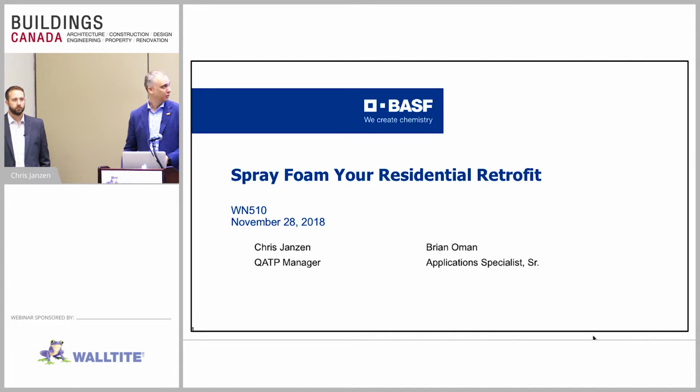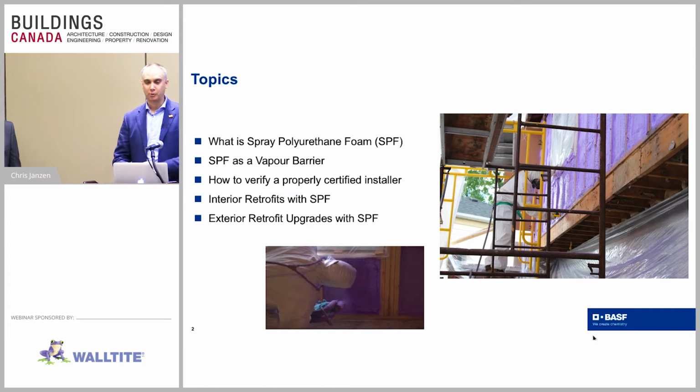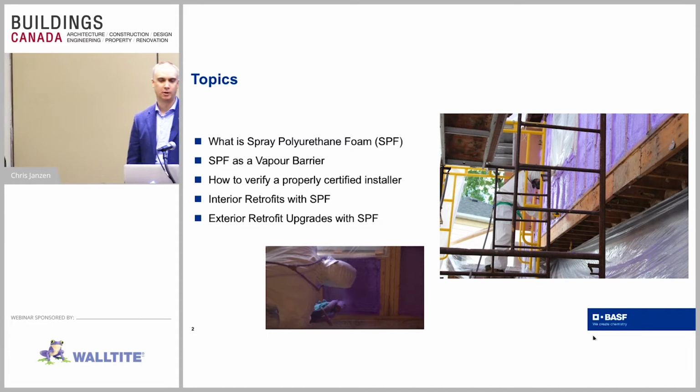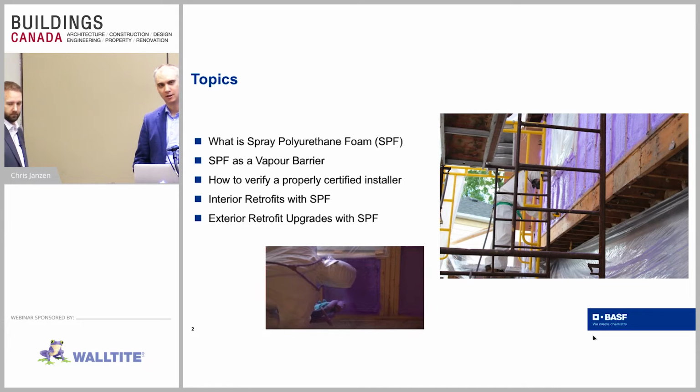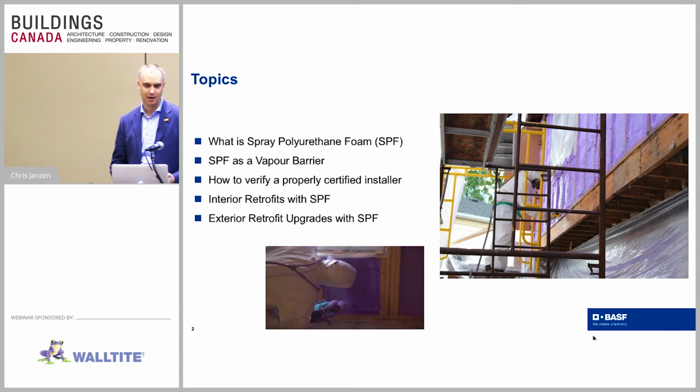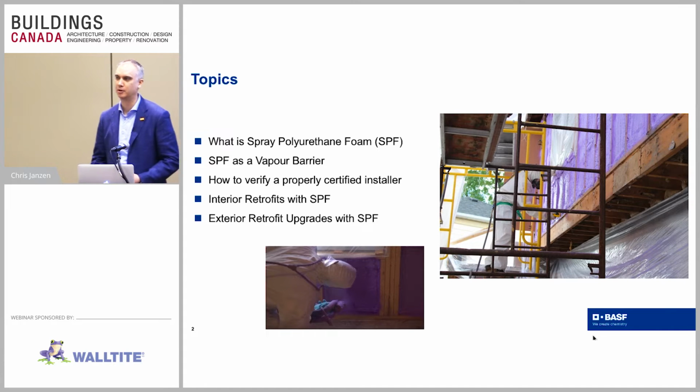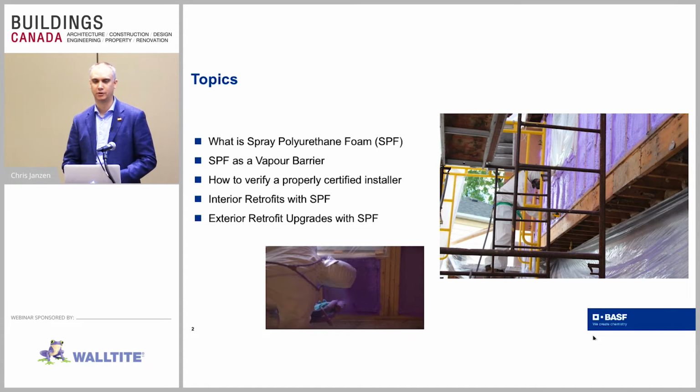We've got about 35 slides or so, we should be done in half an hour, 40 minutes, and lots of time for questions if you guys have any. Some of the stuff we'll be talking about is the very basics about spray foam. What is spray foam? How it functions as a vapor barrier, and why you can get rid of 6 mil poly when you're using spray foam in your walls, and how to detail properly to have a complete air barrier system in a retrofit wall situation.